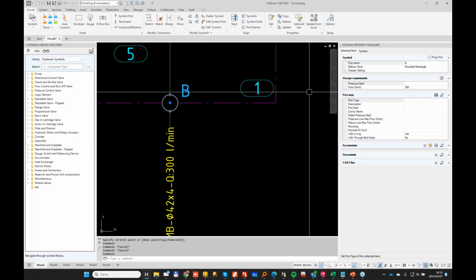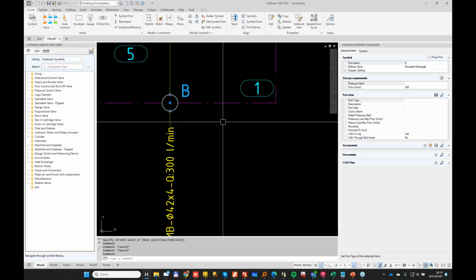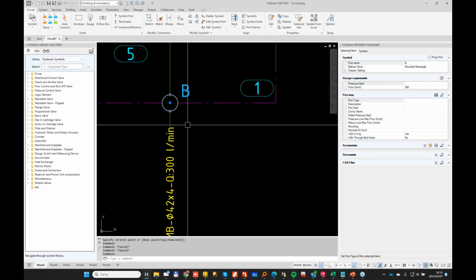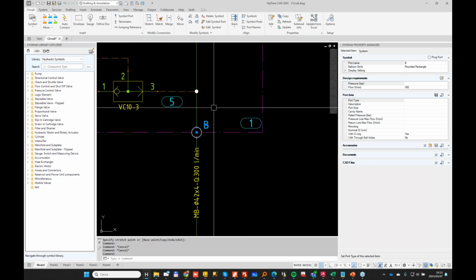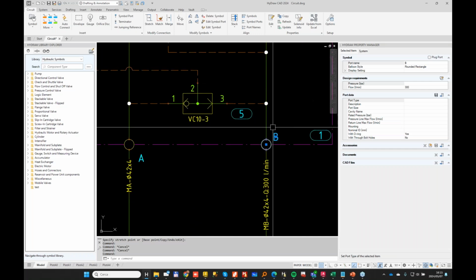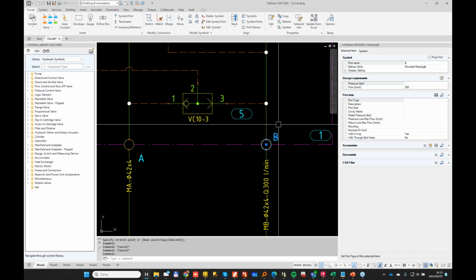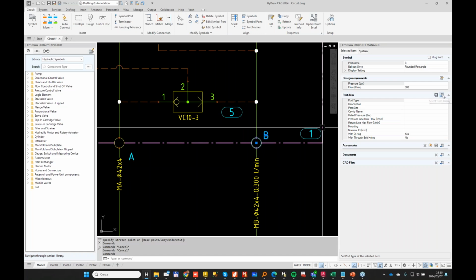Recently, I've been finding a customer that was needing not the fitting for his system, because he later was going to request directly the assembly of the manifold with the fittings inside. So he didn't need the fitting directly on his bill of material. So one technique to handle this is really to go for ports.